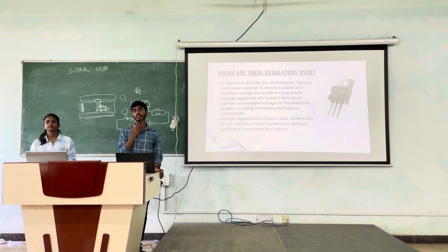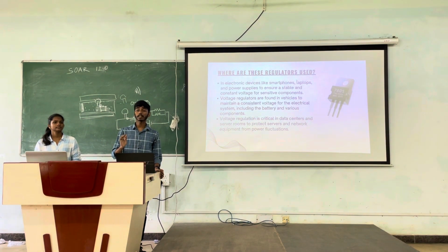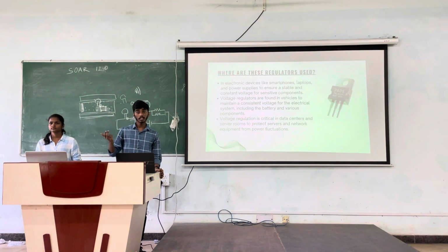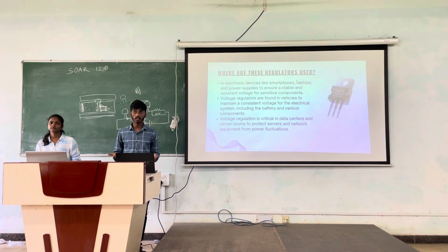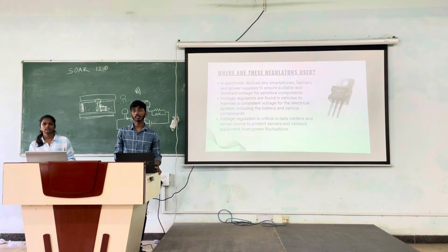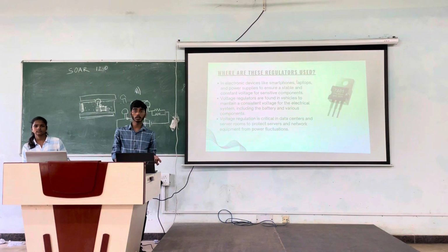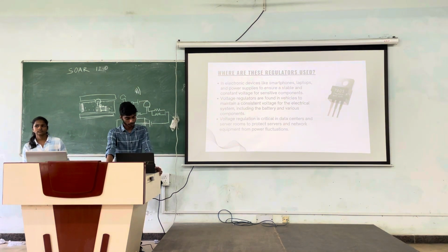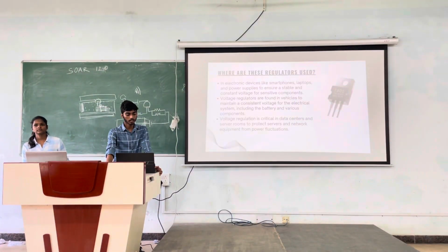So the answer behind this is that we have an application of voltage regulators in cars also: we need to maintain an optimum charging voltage for the battery, so that it does not exceed a particular voltage. If that voltage exceeds, the battery may get damaged or heat up so quickly that it won't work further. So we have this application in a car also, where the voltage regulator is put into the circuit before charging the battery.